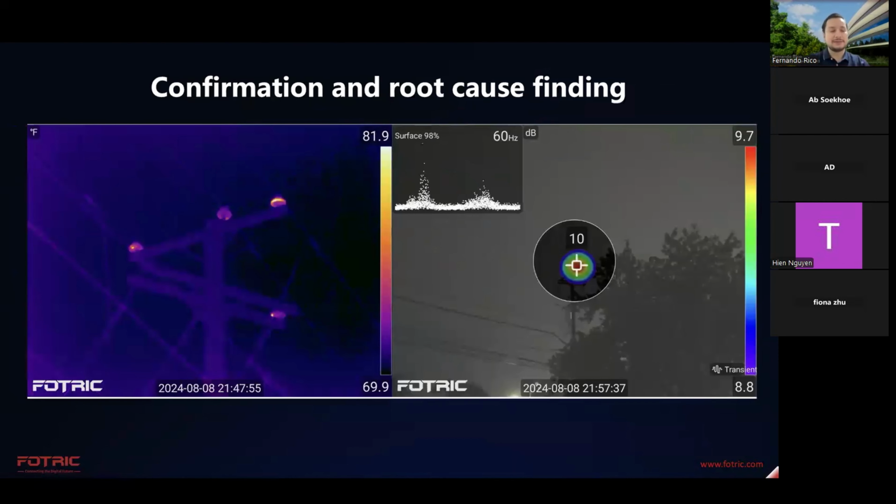I went back sometime later, and now I was seeing actual heating on the insulators. This is not a regular heating. You can see there are specific sections of the ceramic insulator that are hot. Here's just in a specific part. This one you can see that is in the back. Here you can see that is all along horizontally. So these heat patterns are common for tracking events.